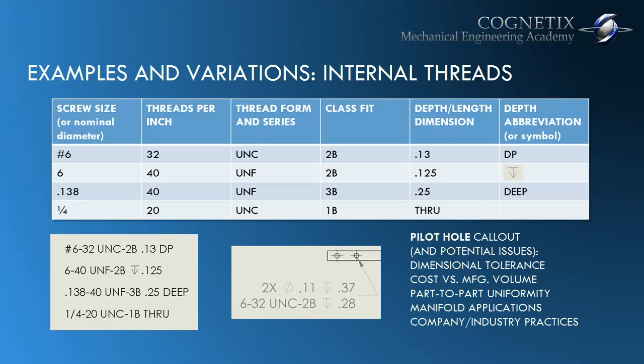Looking on the lower right, the image in the middle, you see that there's also a pilot hole dimension called out above the thread specification.